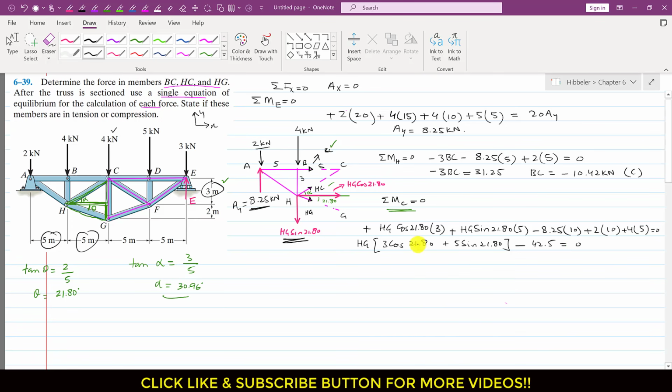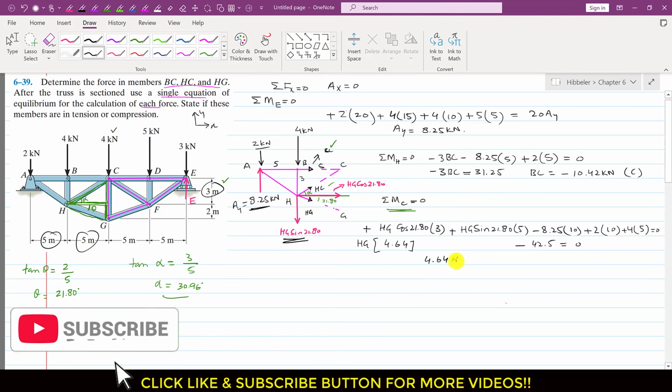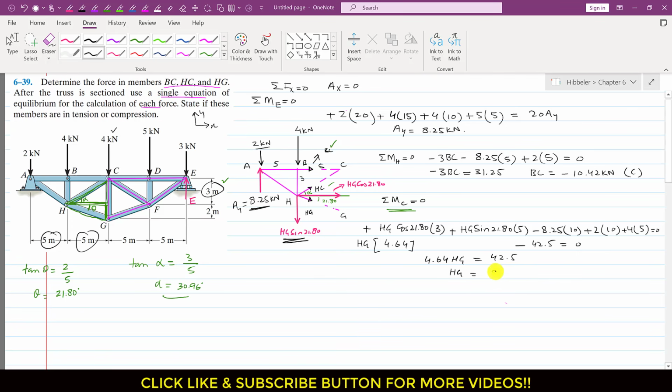And if I add both of these using the calculator, this gives me 4.64, right? So this will be 4.64 HG. And if I bring this to the other side, I will have 4.64 HG equals 42.5, and if I divide both sides of the equation by 4.64, this gives me HG equals 9.16 kilonewton. And since the sign is positive, this means that the assumed direction of HG is accurate, that is acting away from this point H. So this means that this is the tension force, right?